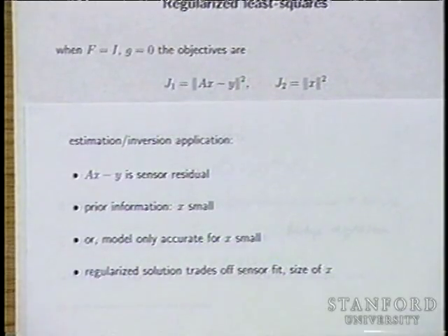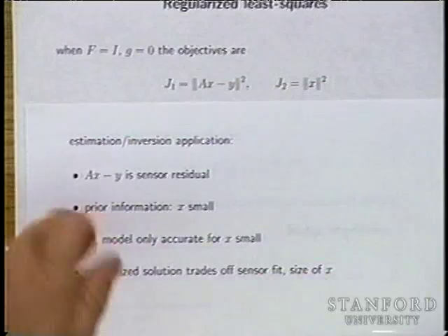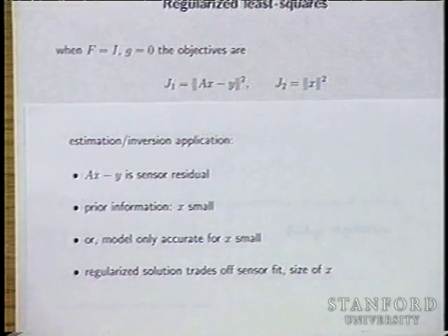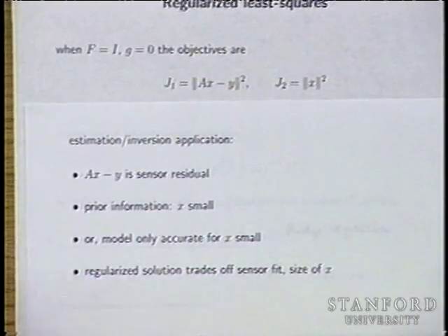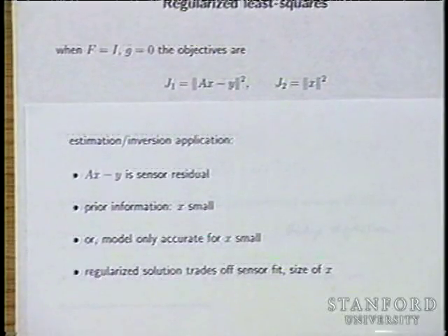As you turn mu, if you turn it all the way one way, you'll get a control system that's very, very slow and doesn't do such a great job, but it doesn't use huge forces. You turn the knob all the way the other way, and you'll get something that's very snappy and is using very big forces or things like that.